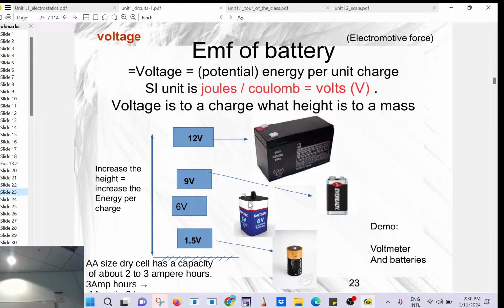M means milliamps, 10 means 10 amps, the maximum. I'm going to put it in voltage to 20. So what you do here, you have your probe. This one goes to positive. The black is always in COM, which means common ground.